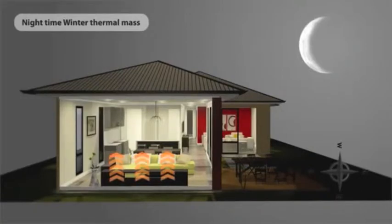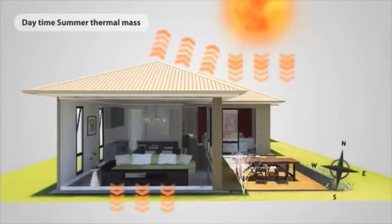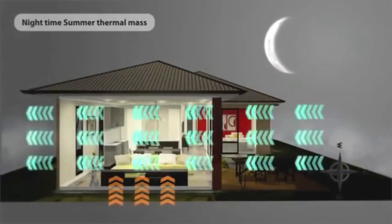The summer sun is higher in the sky, so with the correctly sized and proportioned eaves, you can keep your house cooler by keeping the sunlight out. During the day, the heat inside the house is absorbed by thermal mass, which is cooler because it is in contact with the cooler earth. At night, as the air cools, thermal mass releases heat back into the room, maintaining a consistent temperature.